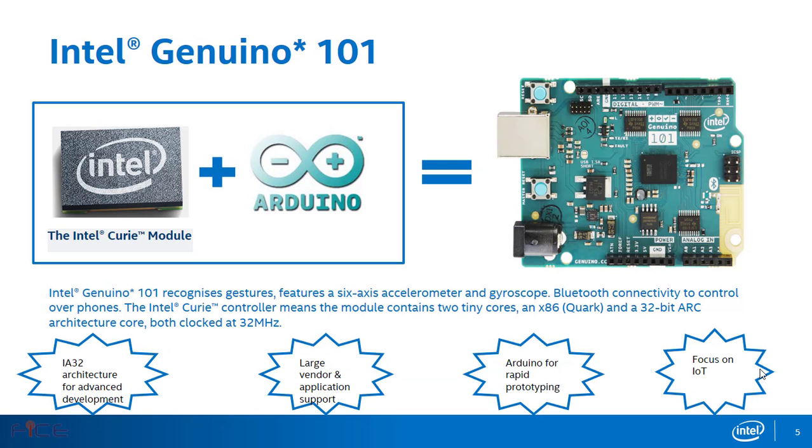In this slide, we will talk about the Intel Genuino 101 that uses Intel Curie microcontroller. The 101 has some features in common with both Uno and Zero, which are 32-bit microcontrollers, but the low-power Intel microcontroller, onboard BLE, and motion sensors make it unique. Intel Curie is a very powerful device, and combining it with Arduino gives users huge flexibility and support to develop applications.